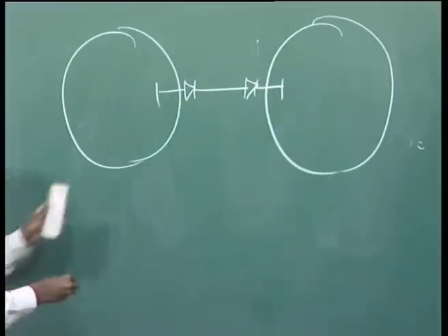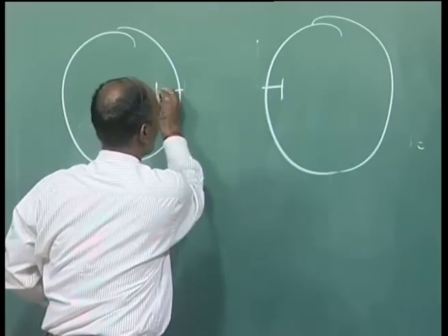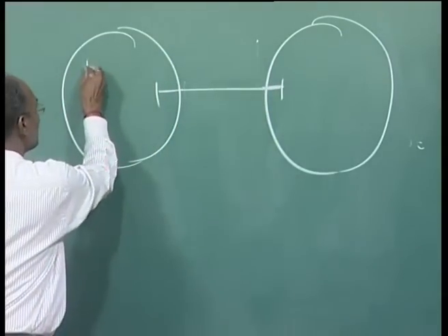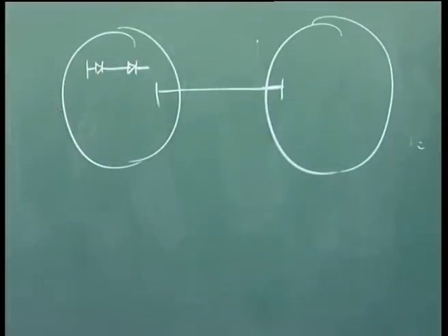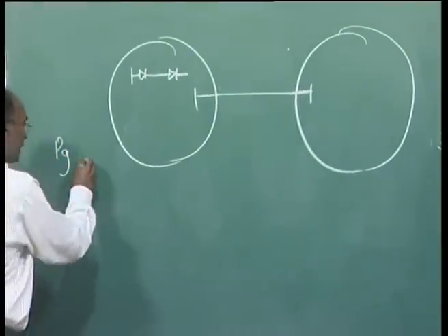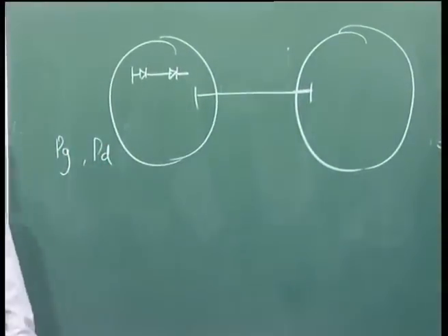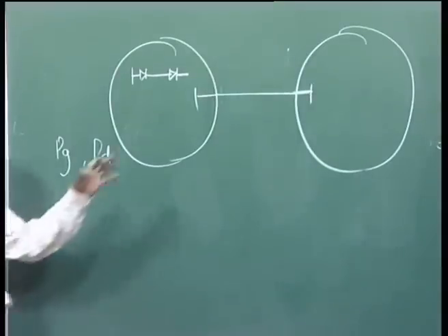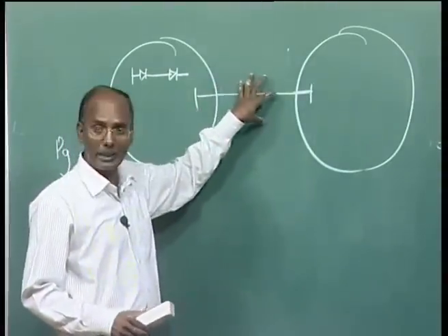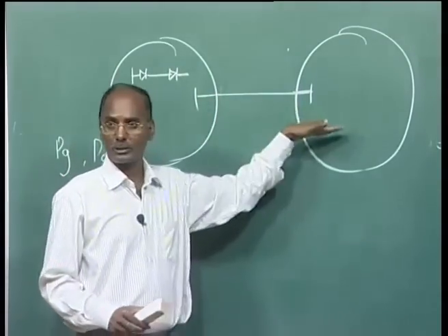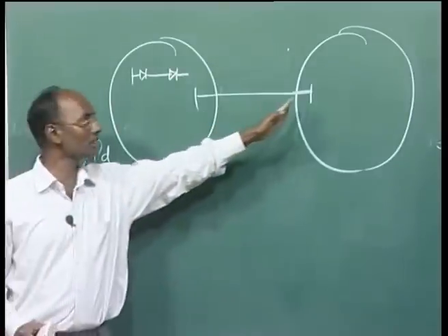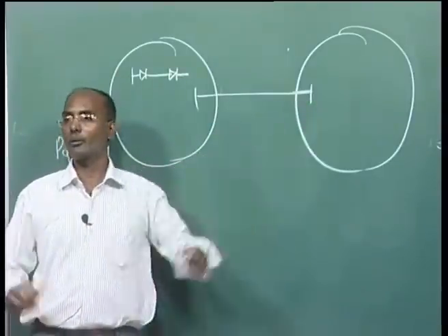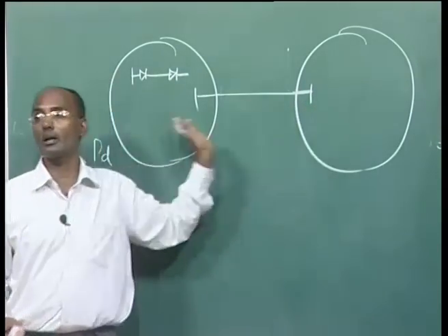But if you have an AC line and a DC link somewhere in between, you cannot do frequency control at all, because then it is always your generators and your demand that will set the frequency. With this connection, you can inject more power into the system or withdraw more power. Basically, this bus is just like a generation or load bus, and therefore you can control the frequency of either this area or this area.